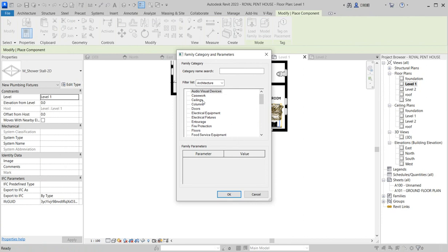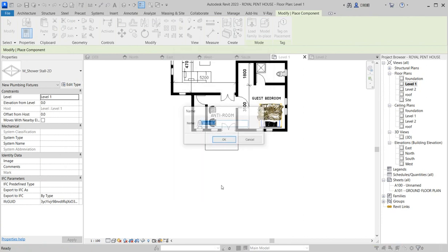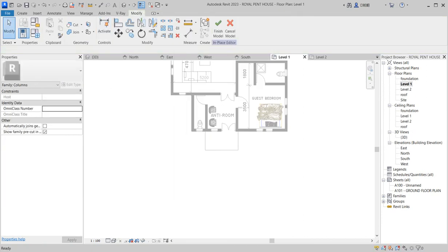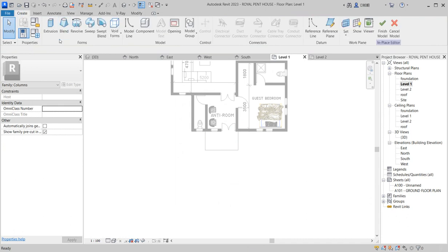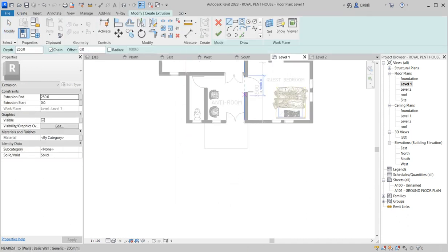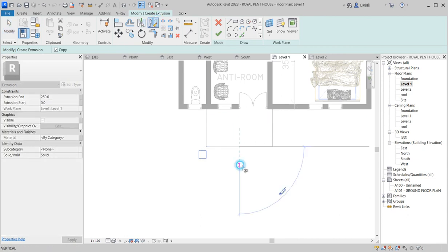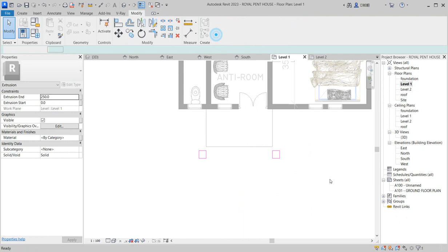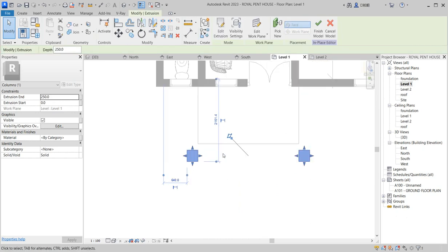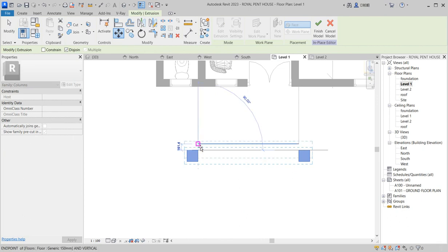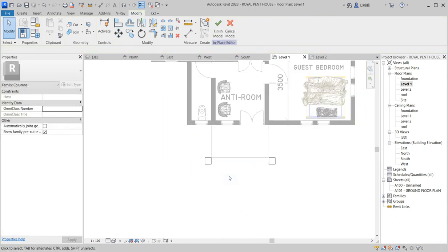So using model to do that, you say column and you say create. So you create that one by using rectangle. I say create and use extrusion. Click extrusion. So from this one now you click on extrusion and you design this based on your own particular orientation. So you do that and then you fix this one in place for now. So click finish. So this one is done for you. So you can bring this back a little bit. Let's put it at the edges like that.